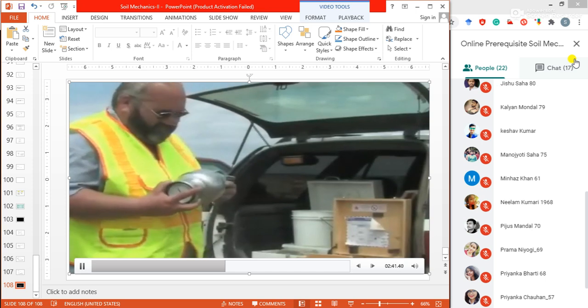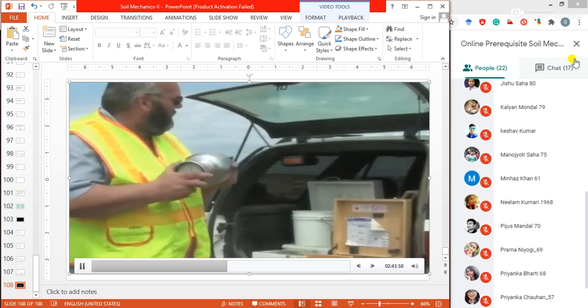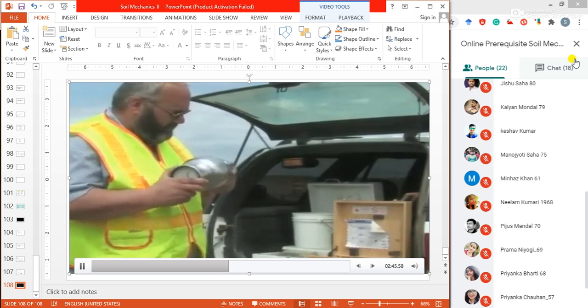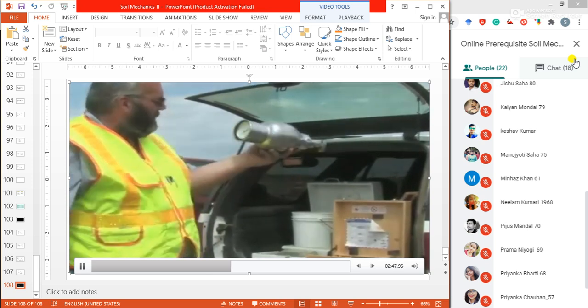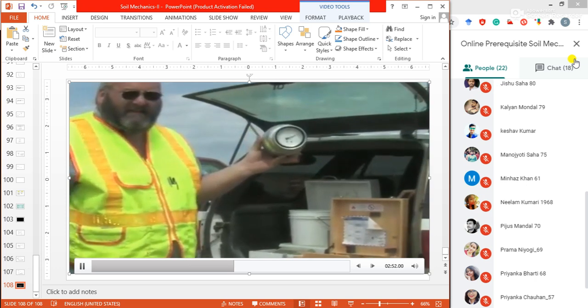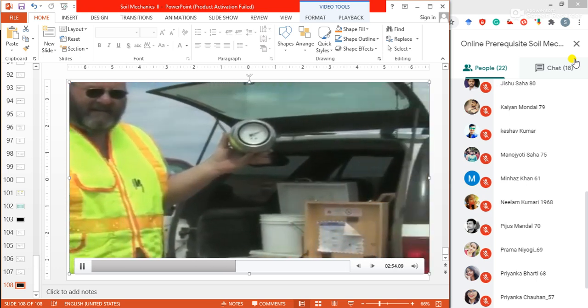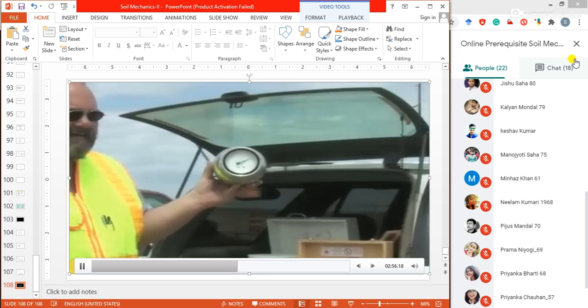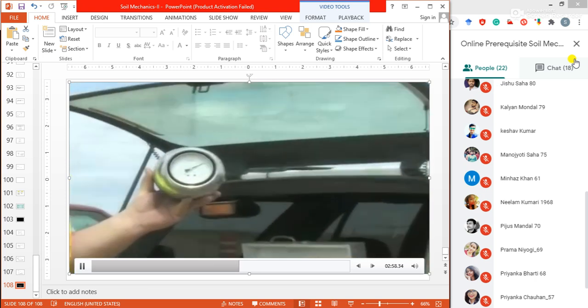Continue this cycle of shaking and resting for at least 3 minutes. Check the gauge reading after each cycle to see if there is an increase in the dial reading. When the needle stops moving, hold the instrument at eye level with the dial facing you. Read and record the dial reading to the nearest 0.1%.